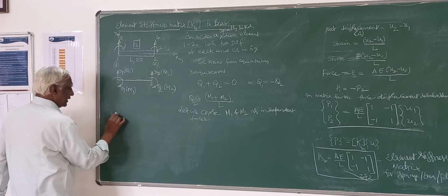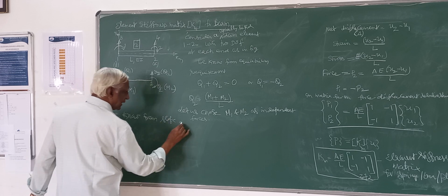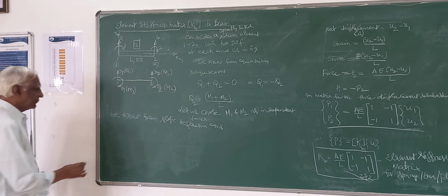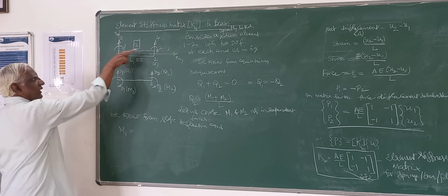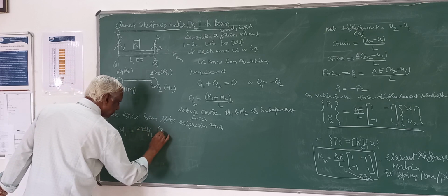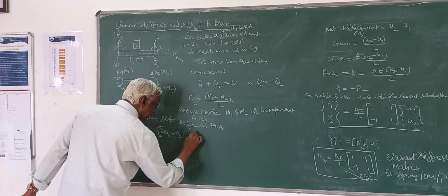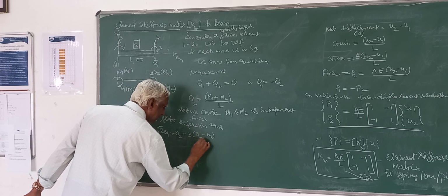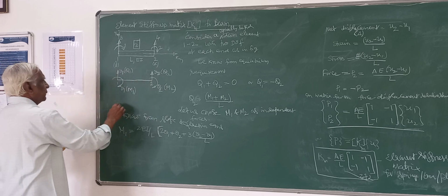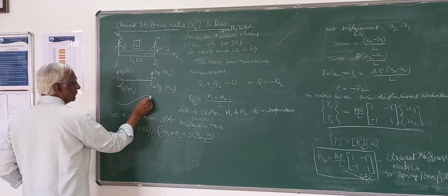Okay? So we know the slope deflection equations which already you know at undergraduate level. So the moment M1, that is the MAB, is equal to 2EI by L into 2 theta 1 plus theta 2 plus 3 (V2 minus V1) divided by L, 3 delta by L. Delta is net displacement, because this displacement you can take it in this fashion, right?